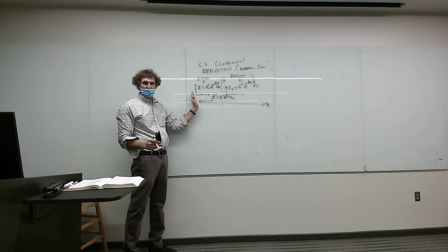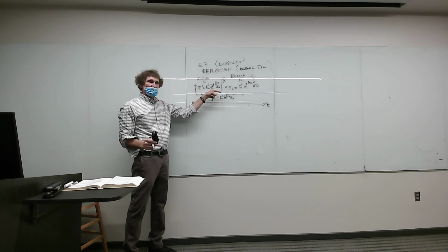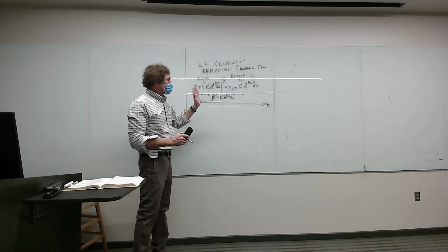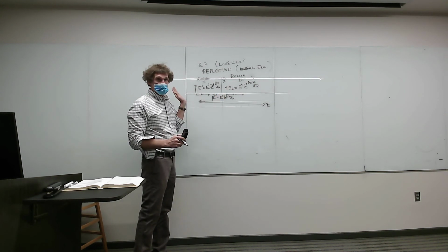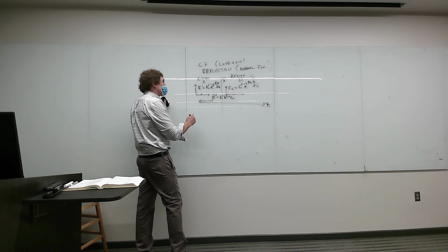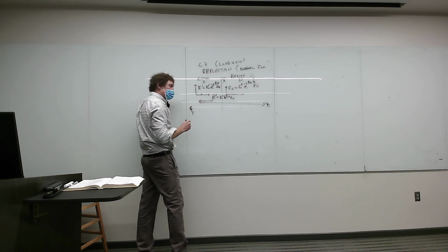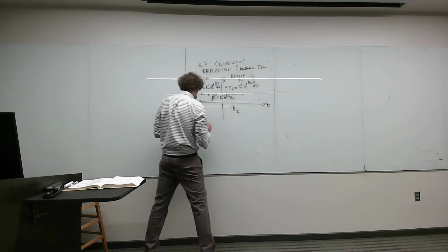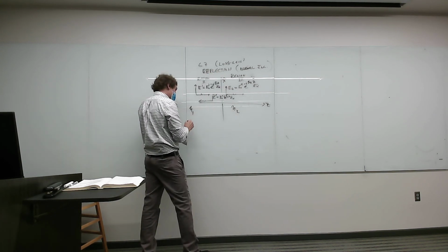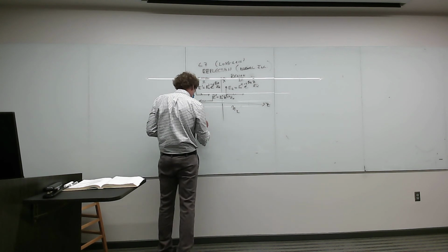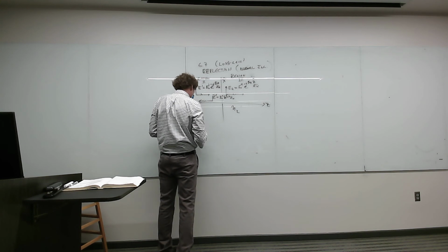I'm just showing you this here. I'm going to break these out when I start doing math on them, all right? You've got an electric wave going in, electric field in the x direction, striking this surface between region 1 and region 2. Some of it's transmitted, some of it's reflected. Now, each of these two regions has possibly different impedance. I'll call this one eta 1, that's intrinsic impedance. This region will have an intrinsic impedance eta 2. This region will have some beta 1, if it's lossless, equal to omega times the square root of mu epsilon.